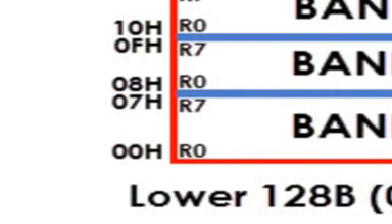Initially it points towards this location, that is 07, but whenever I try to store something onto that stack, it will first increment by 1, then store the value. So it will increment from 7 to 8, then the value is stored on 08 location.